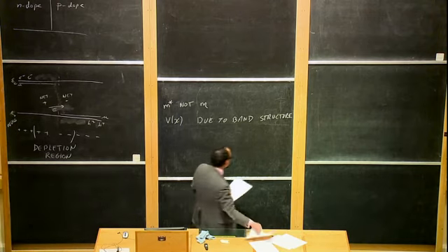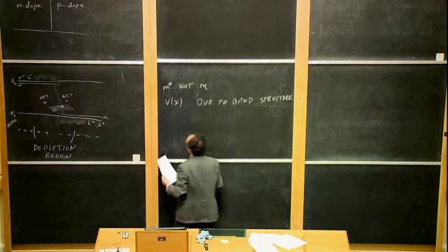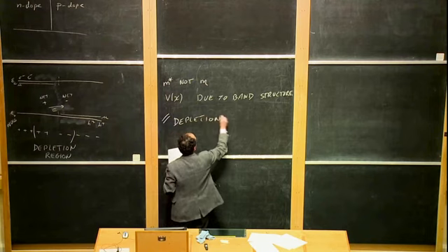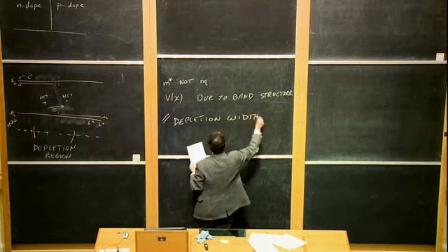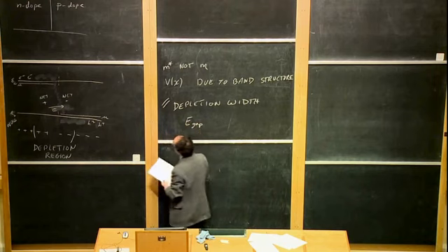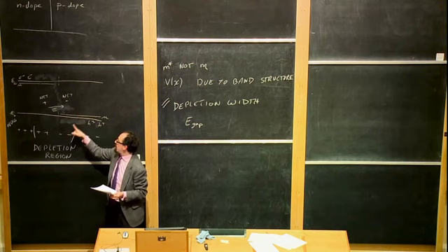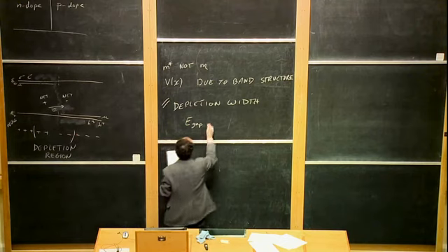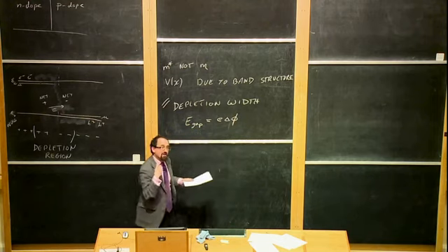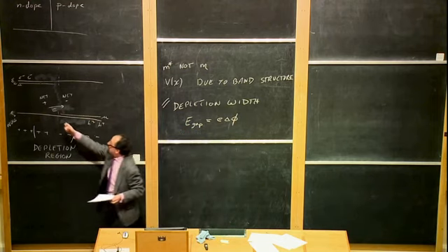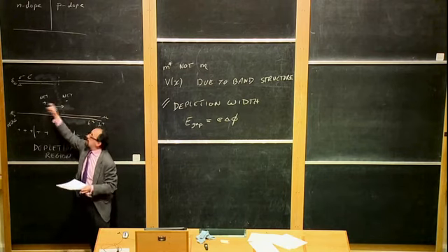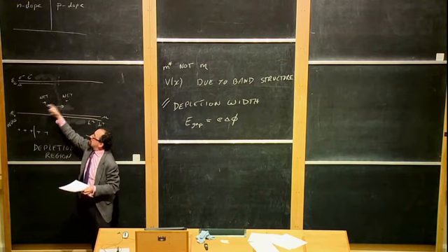So the depletion width is set by setting the gap energy, E gap, the amount of energy you would gain by annihilating one more electron with one more hole, has to equal E times delta phi, the amount of energy you have to put in to get the electron over the electrostatic hill that you're fighting against to move the electron past this charged region.